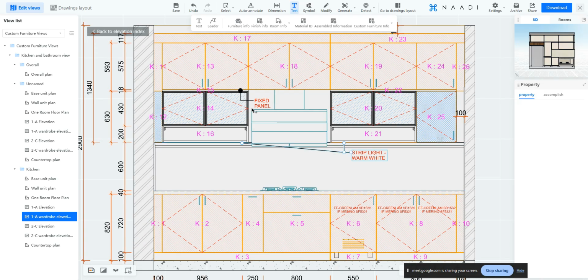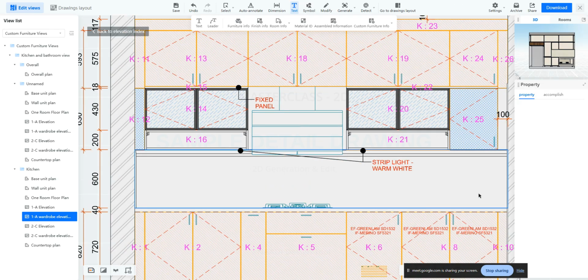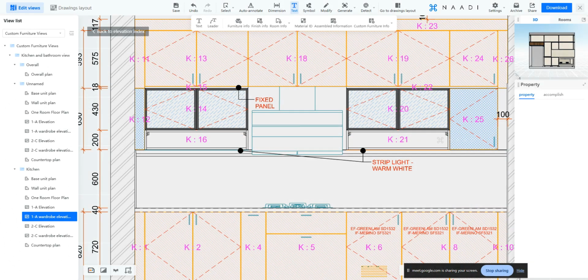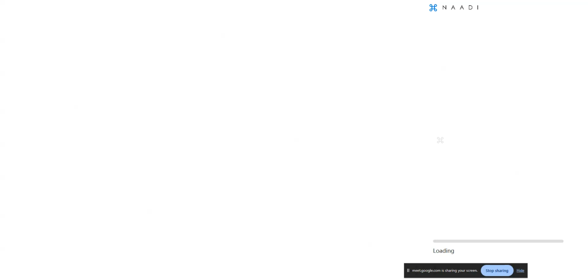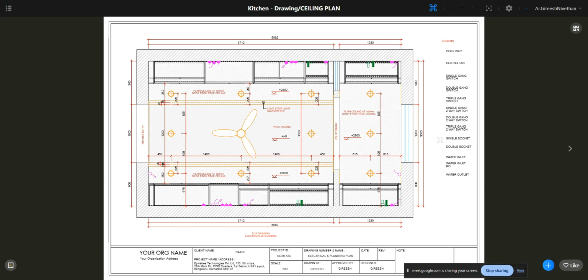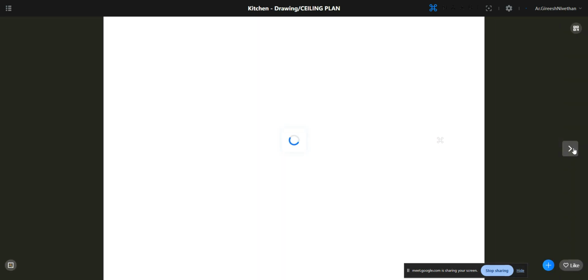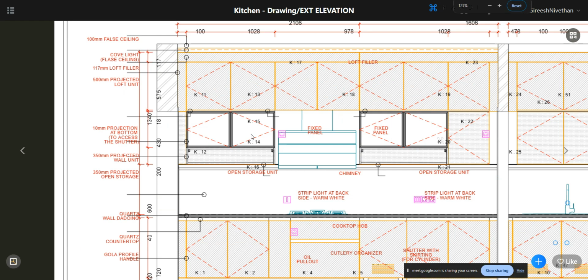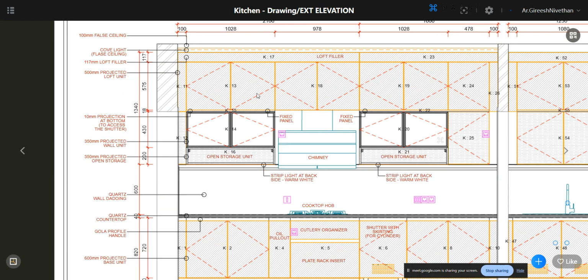And if you want to add symbols here, electrical symbols and all those things, you can add it here itself. And once this is all done, I'll show you one sample drawing which I generated this weekend. This is for the same project. I generated an elevation drawing with the focus on the electricals and plumbing. So here, can you see? This one is the external elevation drawing where I added hatches, all the components. So to this precision, you will be able to define it here.